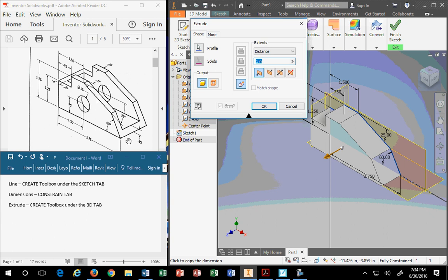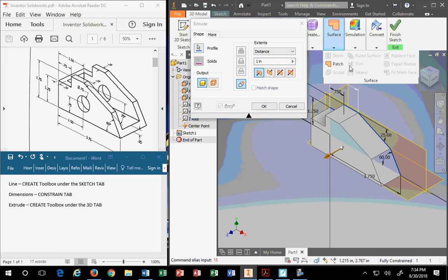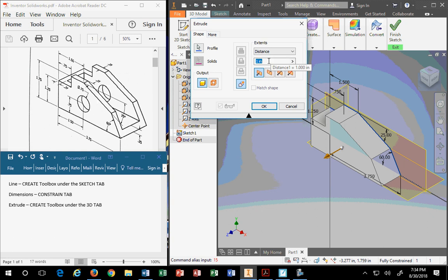Oh, wow. What did the customer forget to tell us? The front to back dimension of this object. But we called him. We knew this. Mr. Jahai called him, right? We found the answer. What's the answer? He doesn't want to say it out loud because it's recorded. The answer is 1.5, if I remember correctly. So we're going to extrude this. Sorry, make sure you're inside the dialog box, right here. 1.5, you type that in.